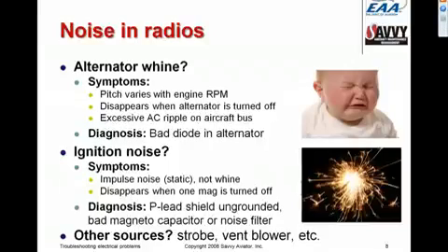It can be a bad magneto capacitor. It can be a bad magneto noise filter if you have one. Most installations don't have a separate magneto noise filter. It can be a defective spark plug.